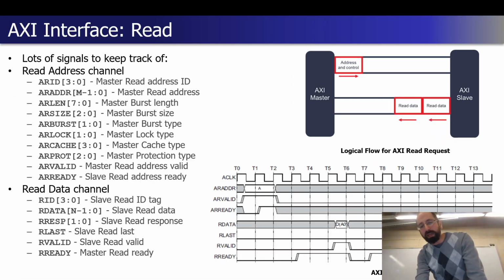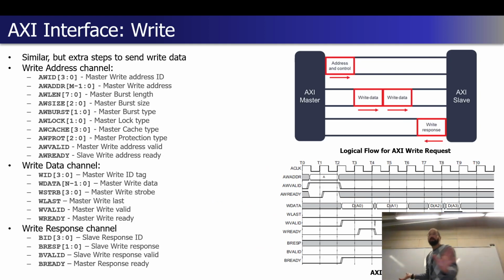That was the read interface. The write interface is just more because there's that third channel here. So there's just 3 steps being shown here with our non-posted write module: handshaking for address, handshaking for every byte of the data that was sent over the channel, and then a final handshake for our write response that yes, everything went correct, everything went okay.